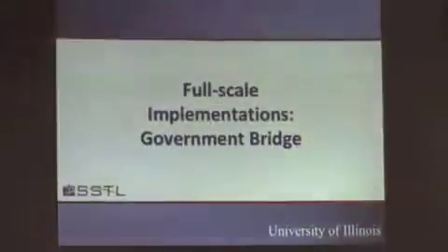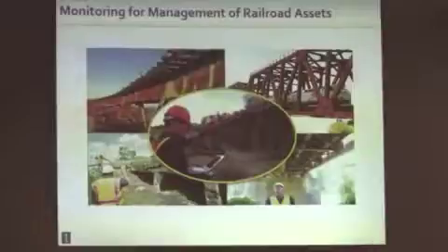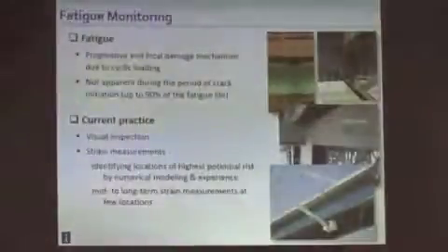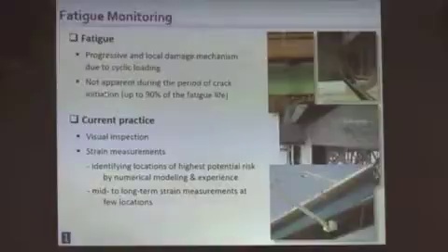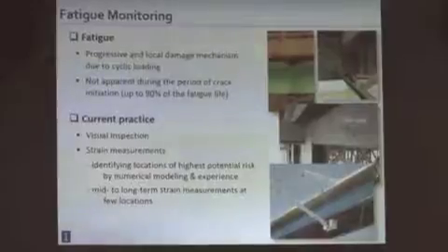Now I'll show you a second deployment. This is maybe interesting because it involves the monitoring and management of railroad assets, and if we look at what I had said about fatigue, this is a particularly challenging problem because up to 90% of the fatigue life is spent in crack initiation. We don't even see the cracks.